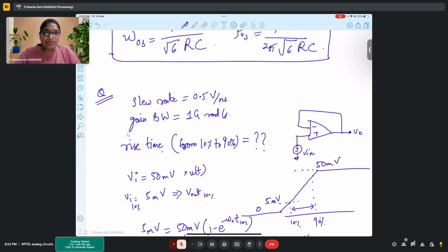Actually, you explained RC phase shift and Wien bridge, right? Yes. They are given some other circuits and they are asking whether they oscillate or not. If they oscillate, what will be the frequency? Yeah, so the Barkhausen criteria is the only thing. Barkhausen criteria is true for all the oscillators. Whether it is positive feedback, negative feedback, whatever feedback it is, Barkhausen criteria works. And if it is positive feedback, we can directly comment that it is oscillating in nature.